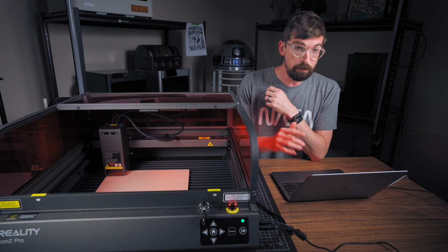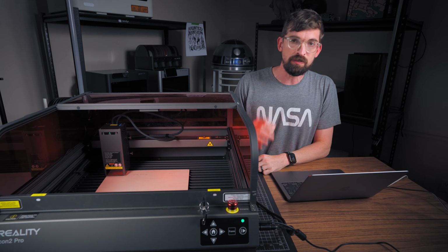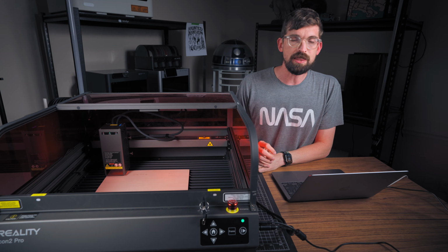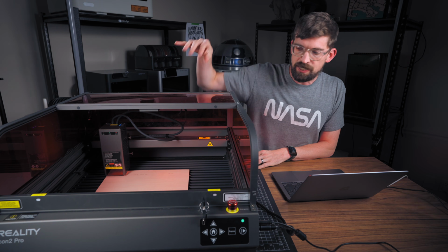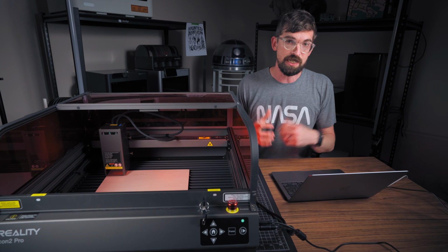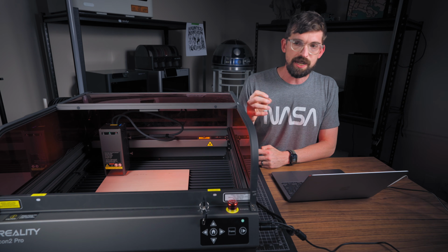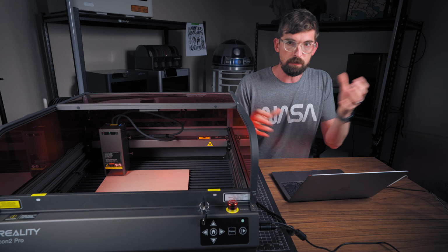the start button. But if you are cutting something out specifically, typically you're gonna wanna do that at the very end of everything that you are engraving, because especially if you're cutting it out from like a bigger piece of material, a lot of times when you cut a smaller piece out, the overall material might shift.